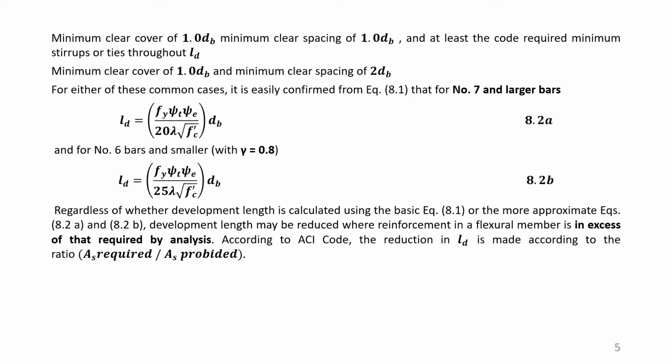And in some of these cases, in slabs, etc., there will be no shear. As in slabs there is no shear reinforcement and the bar spacings are more, in that case we can use the simplified formula. Next.